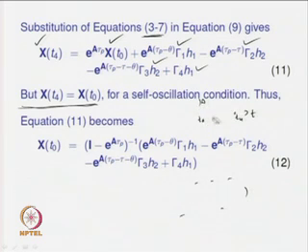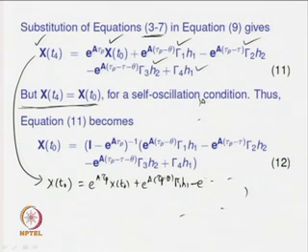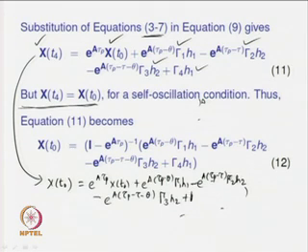When that condition is substituted, equation 11 that we have obtained earlier can be written with x(t4) equal to x(t0). Therefore, x(t0) is equal to e to the power A tau p x(t0) plus e to the power A (tau p minus theta) gamma 1 h1 minus e to the power A (tau p minus tau) gamma 2 h2 minus e to the power A (tau p minus tau minus theta) times gamma 3 h2 plus gamma 4 h1.